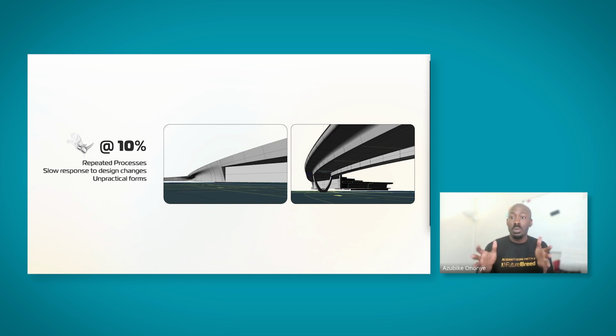You want what they call a rationalization of geometry: you want to use as many repeatable portions as possible. That allows you to come under budget because there's a scale of reproduction of the same thing. However, using Rhino directly, some of the undulation of the form was very, very impractical.